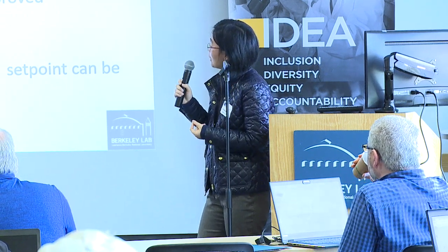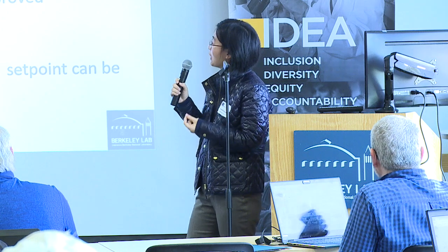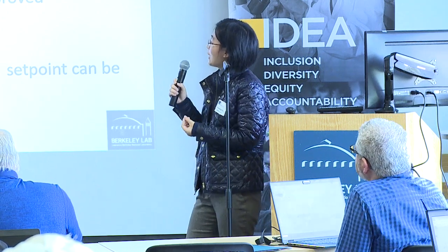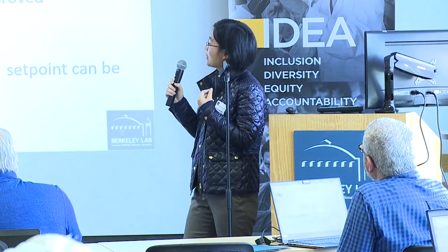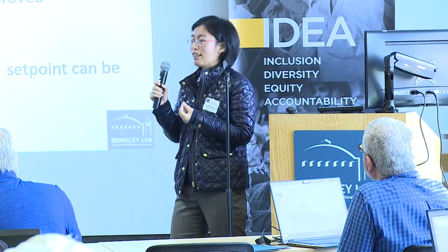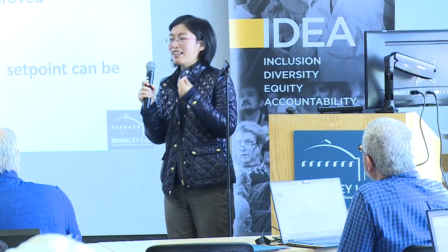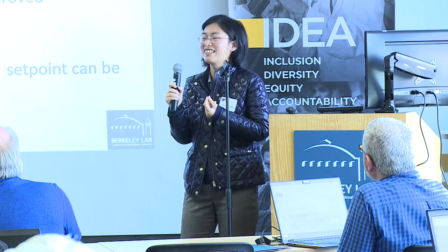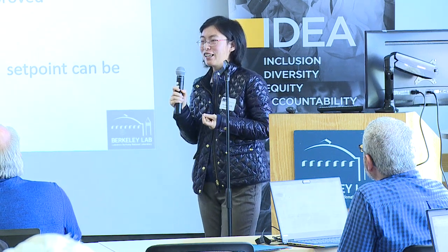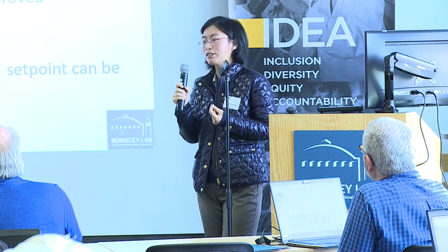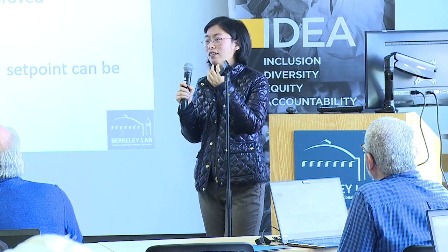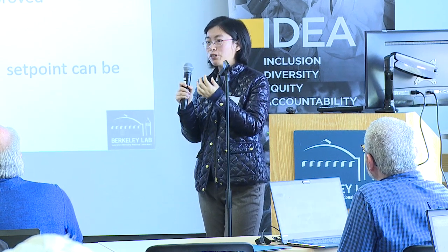And some faults are in between, like sensor reading errors. So I would say that depends. If it is a sensor failure and the reading is 0, then of course we cannot auto-correct it. But if it is a sensor bias, we see a consistent bias that appears in the sensor readings.